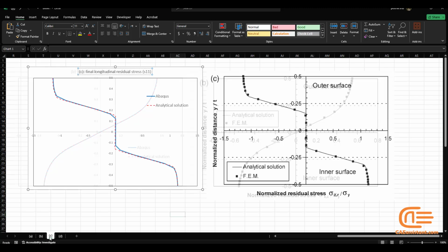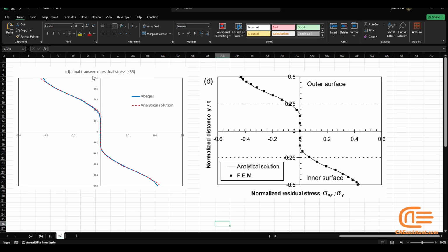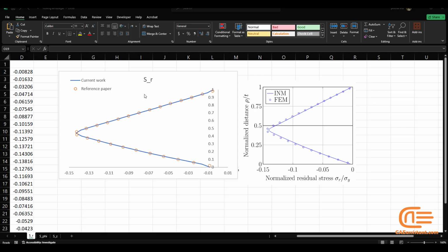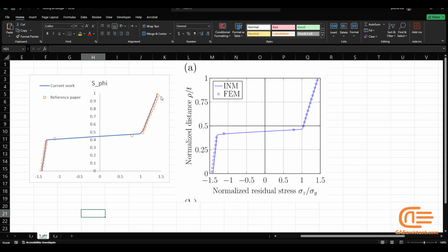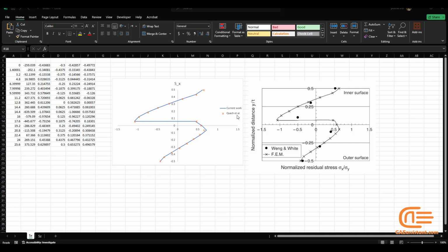In the process of coiling-uncoiling or cold forming, the metal sheet frequently undergoes plastic deformations. Therefore, it is necessary to account for the nonlinear behavior of the material for cold-forming residual stress analysis. Additionally, during the cold-forming process, the metal interacts with rollers and punches. Hence, it is important to consider these complex interactions in numerical cold-forming simulation. Another challenge lies in applying boundary conditions to the specimen in a realistic manner for cold-forming simulation. All of these factors contribute to the complexity of numerical cold-forming simulation.